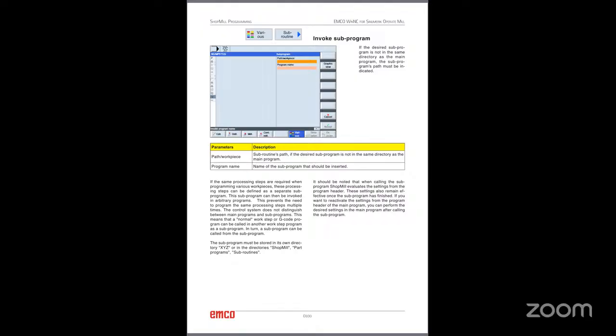So for each workpiece you have, say, center drill and chamfer. If this is the same, no need to write it in the main program. Just prepare it as a subprogram named drilling.spf, and then in your main program, just call drilling.